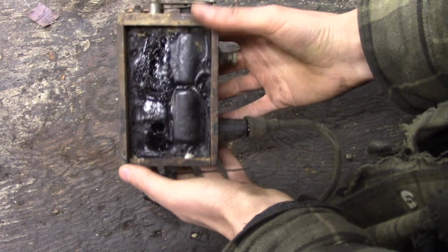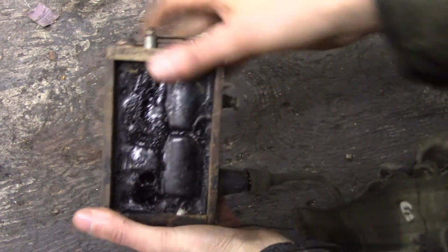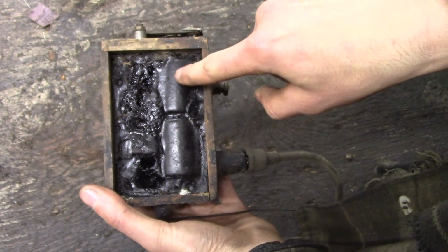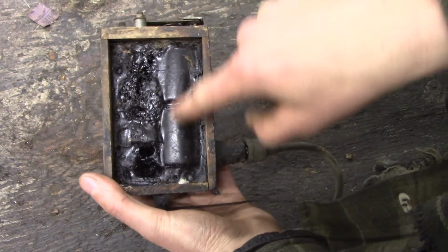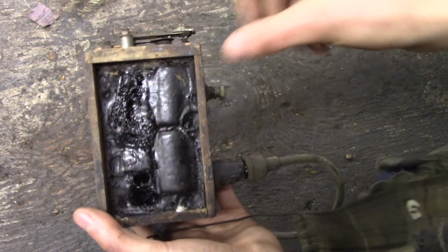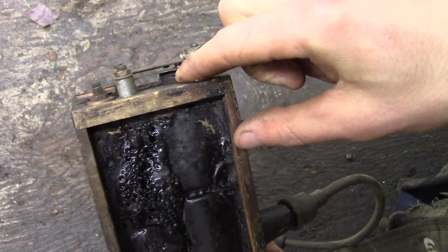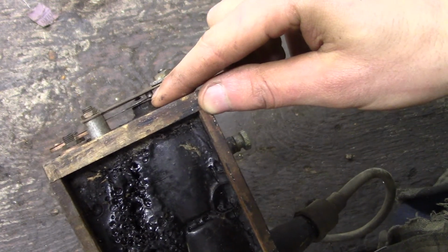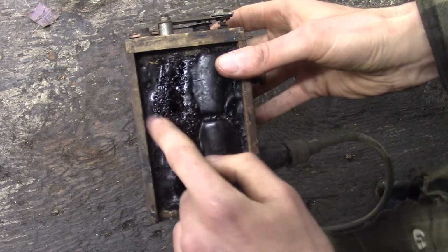But again, here's a look at the buzz coil, and one of the covers is off. It was missing when I bought this one. You can kind of see what's going on inside here. These are the secondary coils. As you can see, there's two of them, and then right through them in the middle is the primary coil, and again you can see the primary right there. That's the iron core of the primary. These are the points, and then hiding in here underneath this tar or pitch or whatever it is, the condenser.